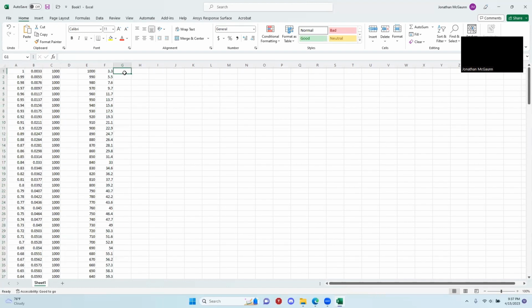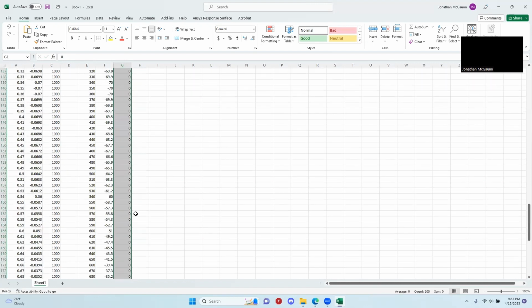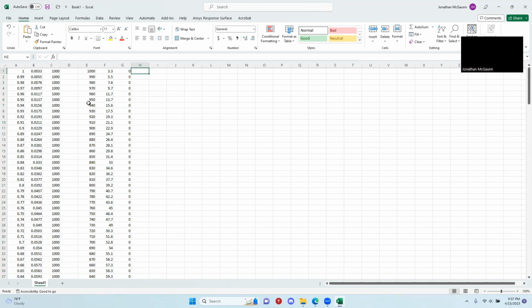Perfect. And then to make your final adjustment for SolidWorks, you actually need to add a z coordinate. Because we're making a surface plane, only two-dimensional, you can just add zeros all the way down in this column here. And that's pretty much all you need for your setup. Again, you can do more manipulation with this if you need to, but this is the general process.